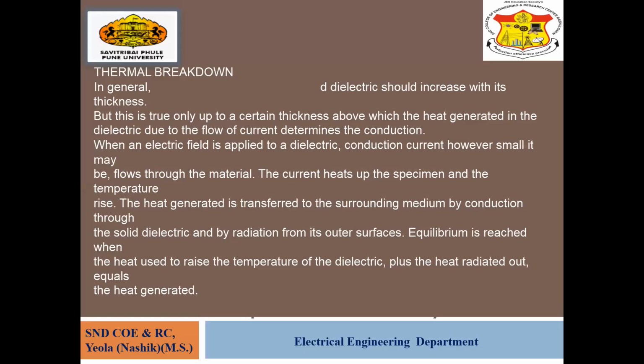Now the next one, the thermal mechanism or thermal breakdown. We know that the dielectric strength of a solid dielectric increases with thickness. More thickness, more dielectric strength. But this is applicable only up to a certain thickness. If the thickness goes above that specified value, then heat is generated in the dielectric due to the flow of current, determining the conduction.